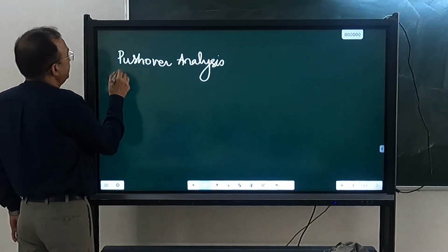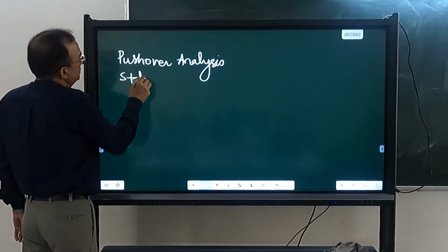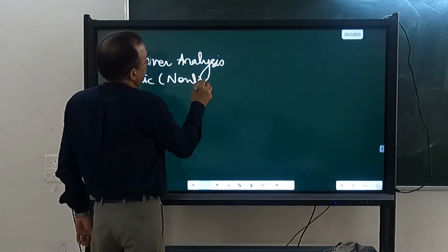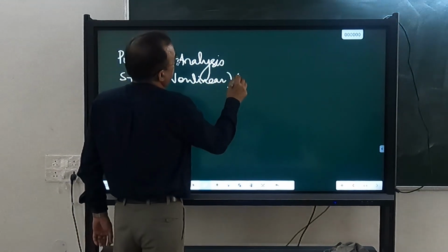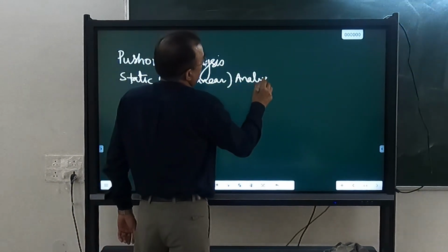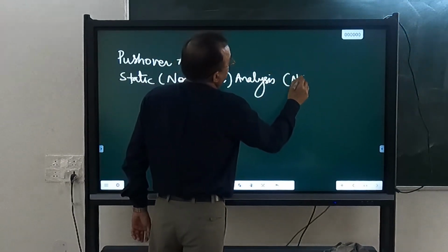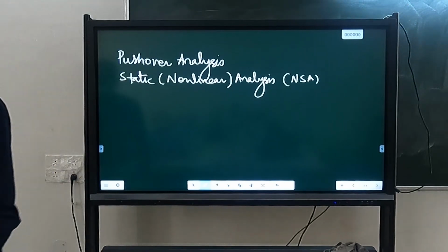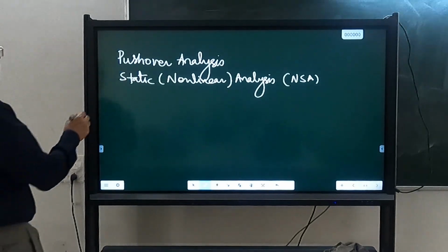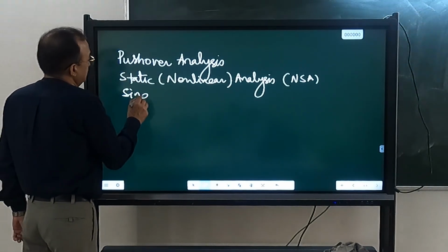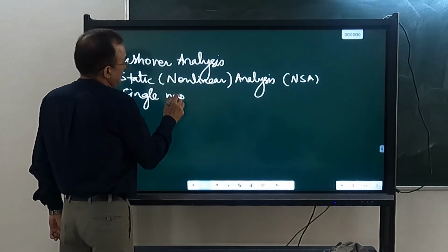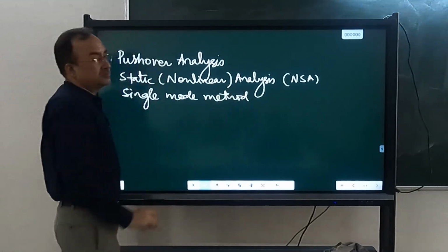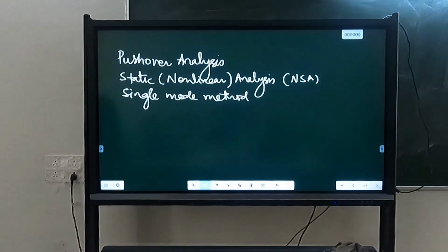Pushover analysis is static analysis, but nonlinear. So this is a nonlinear static analysis. In short, we also call it NSA or NSP, nonlinear static procedure or nonlinear static analysis. We also call it the single mode method. We are considering only one mode.